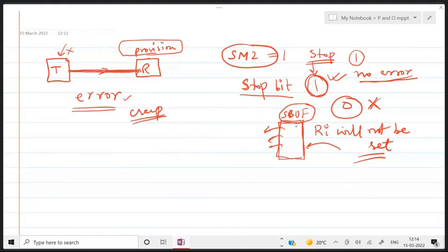If the coming data is again free from error, that means the ninth or stop bit is equal to 1. The question may arise: what if the error itself is causing the ninth bit to be 1?